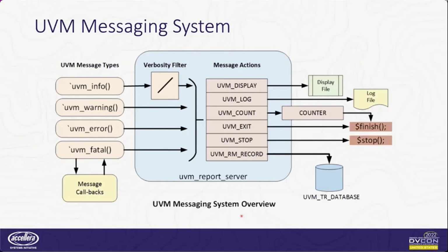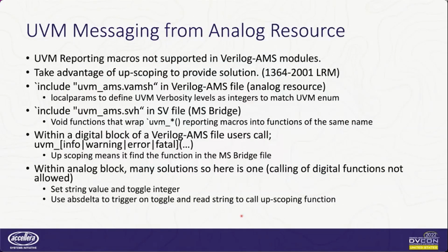So the issue is that they are SystemVerilog macros. And of course, that analog resource is likely going to be a Verilog-AMS module, which means it can't use the SystemVerilog macros. So how do you take advantage of a SystemVerilog macro?